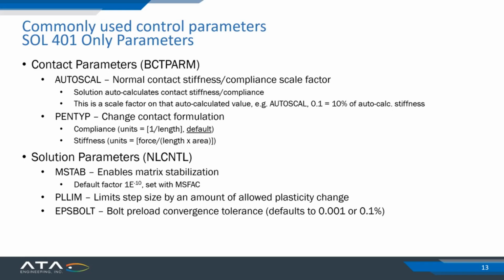It's especially useful if you have a free body that's not connected by contact at the beginning of the solution. It kind of gives it almost like a small, lightweight grounded spring to hold the model from flying off 10 miles to the right in the very first second that it gets any load. Then there's a PL lim parameter, which allows you to limit the amount of plasticity that the solution will allow from one iteration to the next.